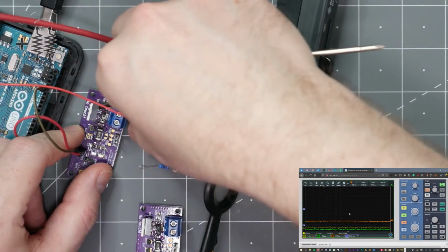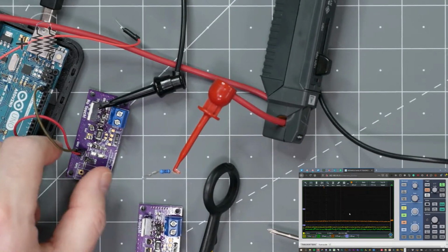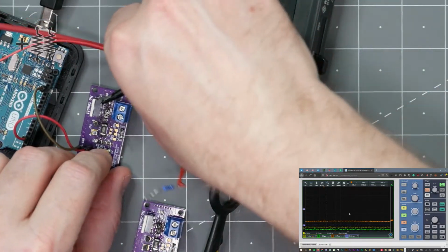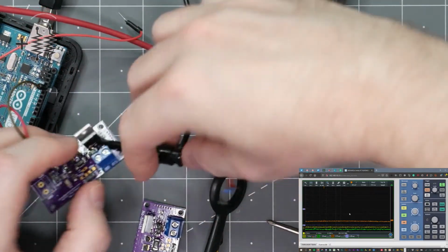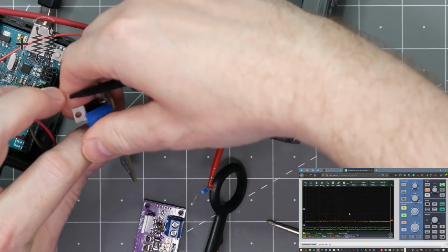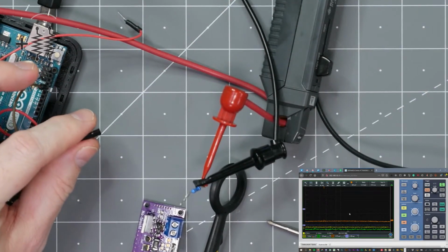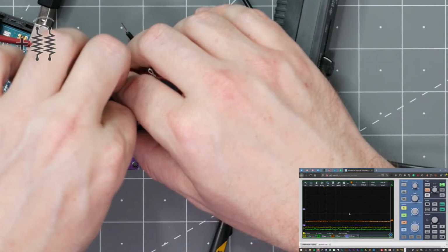And so that's why I have the Arduino turning on and off, so that we get reduced current or reduced power dissipation on it. But it was the only 100 ohm that I had, and I didn't want to go much smaller than that, because then we get into all kinds of other effects.